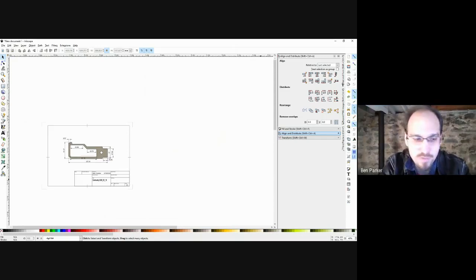As far as the parameters, a lot of times it's trial and error. For wood, I would usually use, I'm trying to think, it's been a while since I've cut on wood, but it was 50 millimeters a second, yeah, 50 millimeters a second, and power 80, I want to say. But again, it's going to depend on the materials.